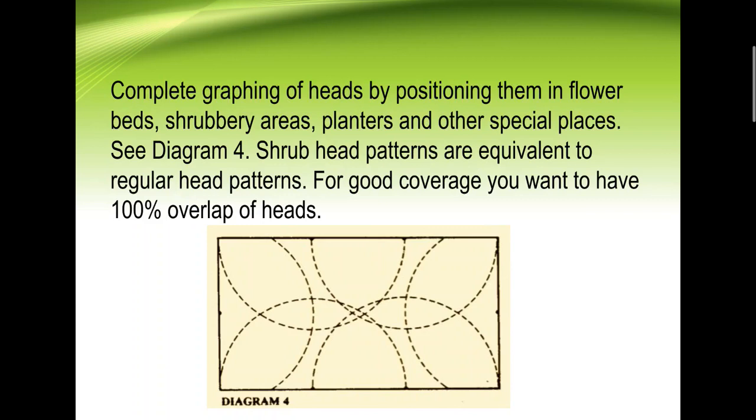Complete the layout of heads by positioning them in flower beds, shrubbery areas, planters, and other special places. See diagram 4. Shrub head patterns are equivalent to regular head patterns. For good coverage, you want to have 100% overlap of heads.